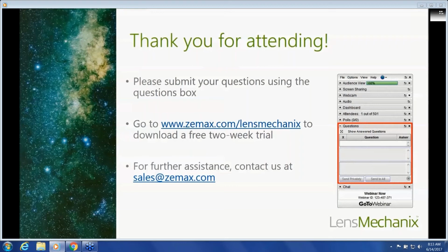We always recommend that if you do add certain sources and they're actually part of the optical design, that they are sent back to OpticStudio. But if you wanted to simulate the sun and see what happens when there are extra sources to the side and how that affects the optical performance, you can do that.